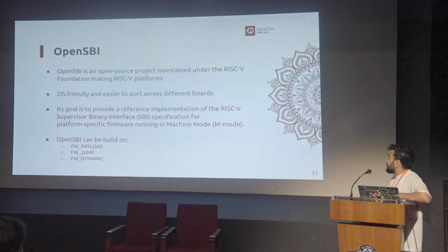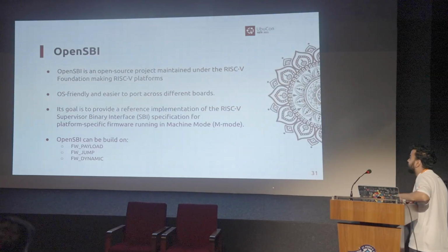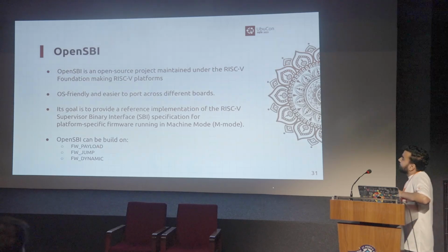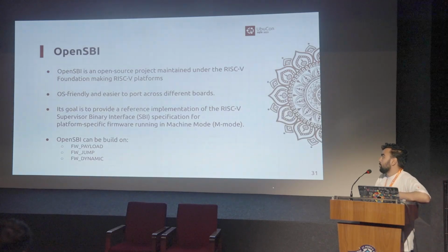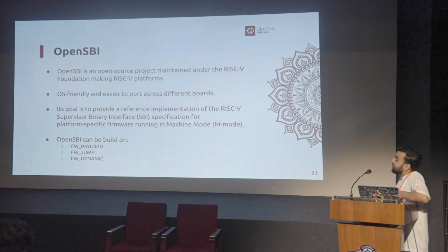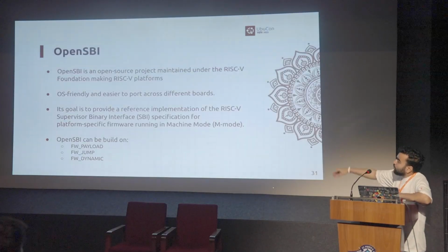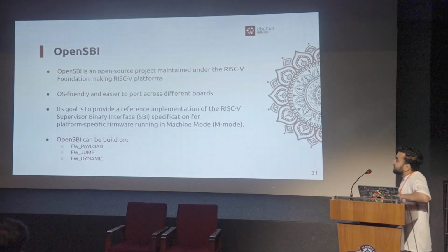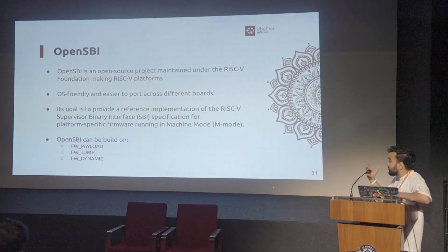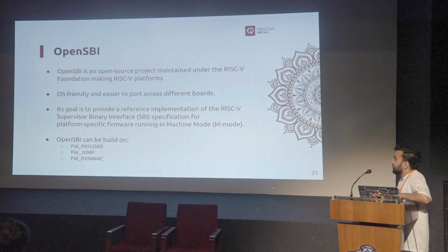And what's OpenSBI? It's an open source project maintained by the RISC-V Foundation, making the RISC-V platform OS friendly and easier to port across different boards. That's another aspect of the open hardware initiative we were talking about. Its goal is to provide a reference implementation of the RISC-V supervisor binary interface for platform specific firmware running in machine mode.